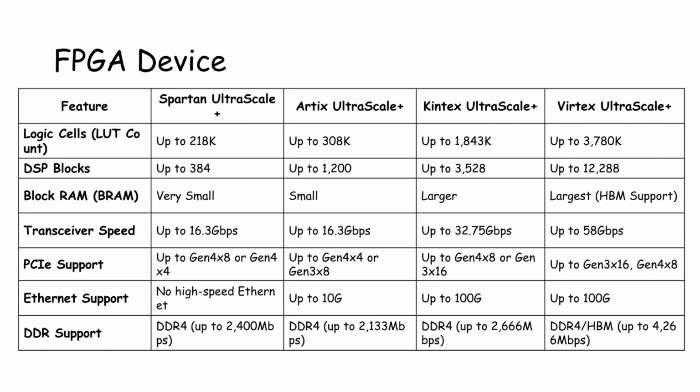As you can see in the comparison table of FPGA device families, there are differences in internal logic cell capacity and various architecture components across models. Before selecting a final FPGA, designers can run simulations, perform placement and routing, and even generate a bitstream based on the chosen target device. This makes it possible to evaluate in advance which FPGA is most appropriate for a given design.